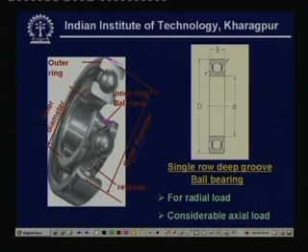That means for this you require to make some sort of seat on the shaft. So, the bearing will come and fit over here, so that when the shaft rotates, the inner race rotates and the outer race is always within the bearing housing.